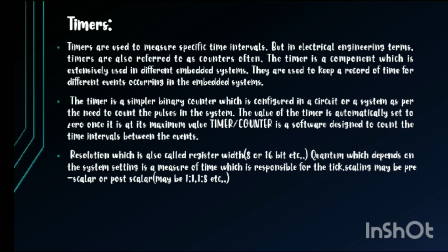The value of the timer is automatically set to 0 once it is at its maximum value. Timer or counter is a software designed to count the time intervals between the events. Resolution, which is also called register width, is 8 or 16 bit etc. Quantum, which depends on the system setting, is a measure of time which is responsible for the tick. Scaling may be prescaler or post-scaler.